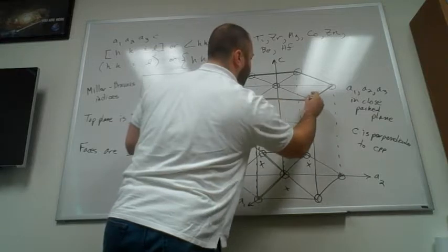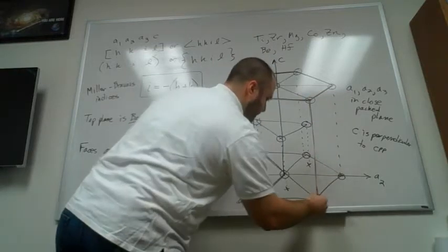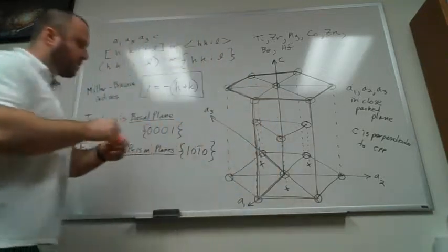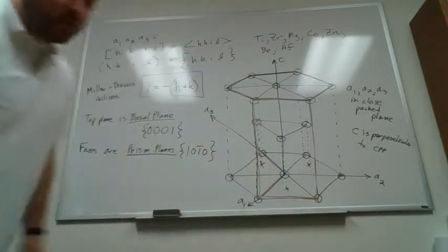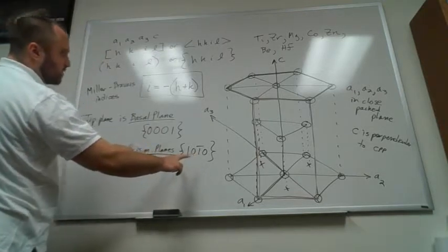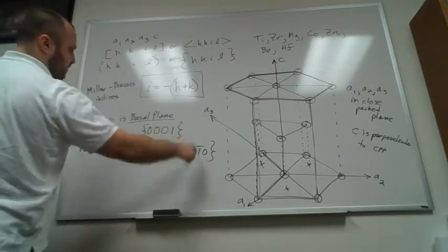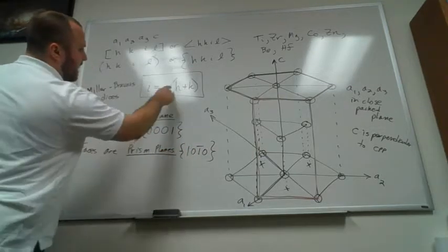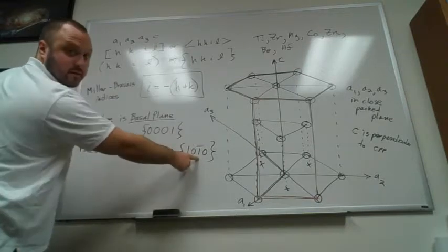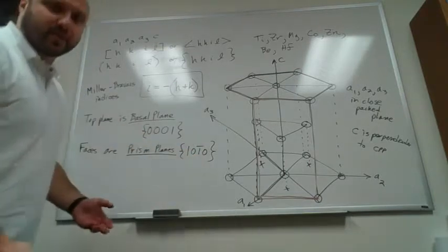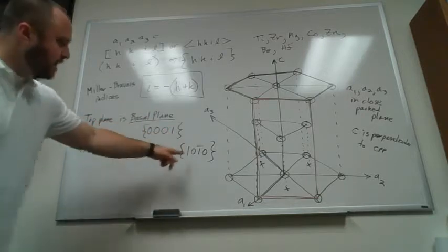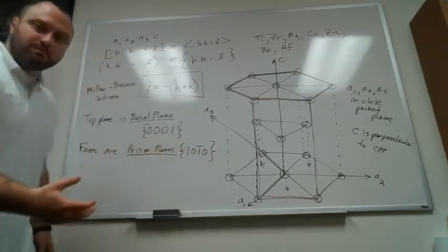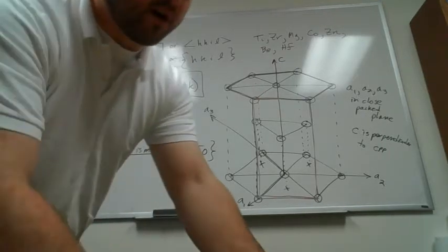For example, one of these is this front face. Okay, that front face is a prism plane. And if you look at that index, I'm using my rules now. Okay, so H is 1, K is 0, so I has to be negative H plus K, it's negative 1. Okay, and that's useful because I could look at other planes, like for example, something with a different combination of these that looks similar, 2 1s and a 0, are related.